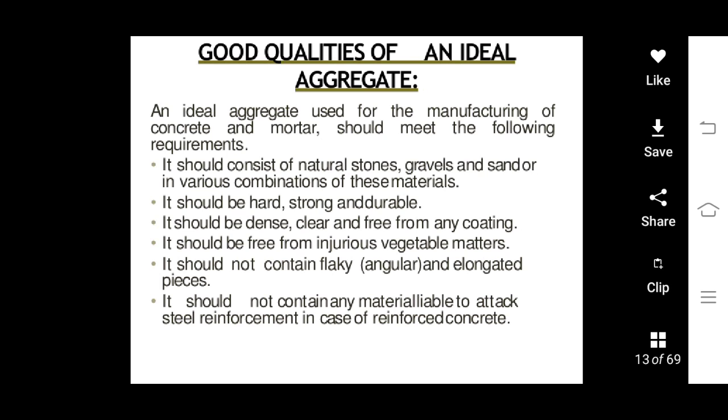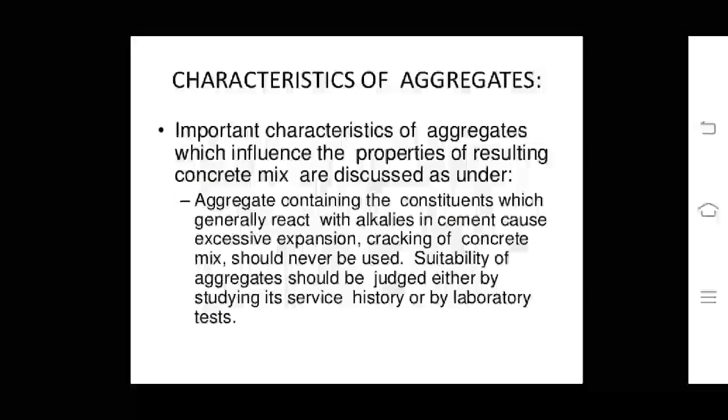It should be free from injurious vegetable matter and organic matter. It should not contain flaky, angular, and elongated pieces of aggregates. It should not contain any material liable to attack steel reinforcement in case of reinforced concrete, causing corrosion of steel.